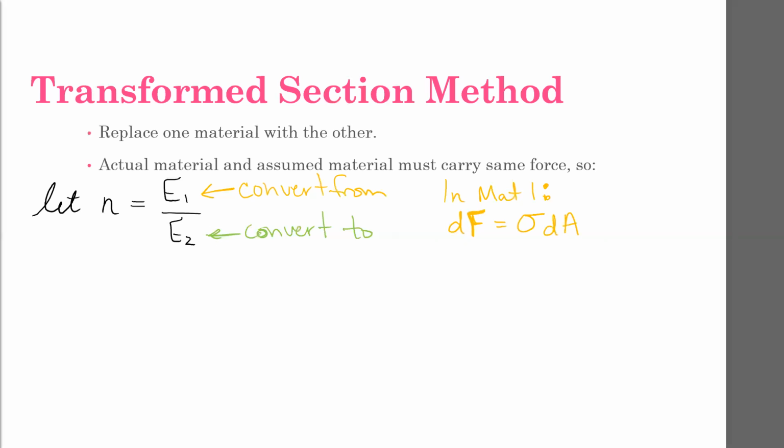You take a stress multiplied by an area, you get a force. And that has to be equal to the modulus of elasticity of that material times the strain experienced. That gives us the stress. And then dy dz gives us the area.